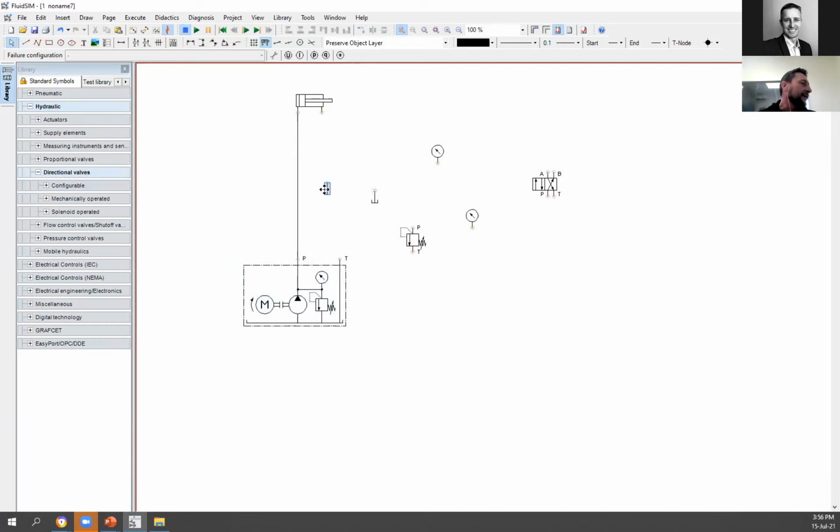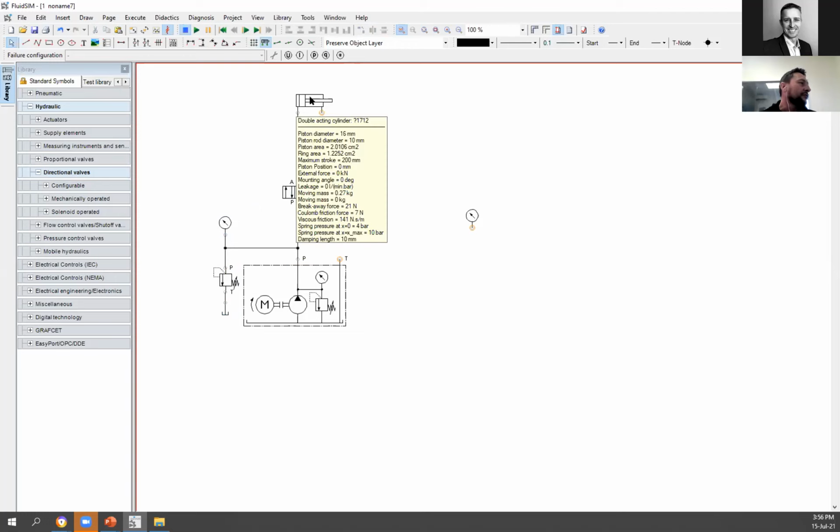Okay, we want to be in control especially because of the unsafe conditions that can arise if you are not controlling your hydraulics properly. So here on the side, I'm just quickly connecting a system pressure valve. This will be a pressure relief valve that will be used as a system pressure. And I'm going to connect the gauge there to monitor that pressure as well. And here on my line, I do not want the oil to flow directly to my cylinder. What I want to have is a control valve in between to be able to control my cylinder.